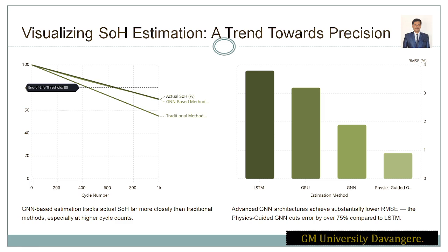Now the real SOH is 85%. We are just taking this as an example. So you can make the prediction with the help of the RMSE that I told about, less than 1%, and it comes to around 83.1 to 86.9 percent, which matches with your R-square values, right? That is around 0.9947. These are used in the premium electric vehicles in most of the cases.